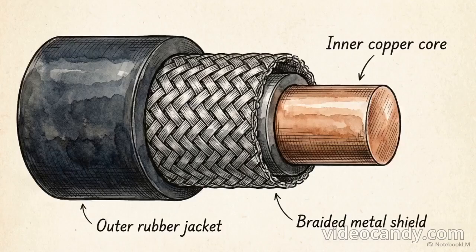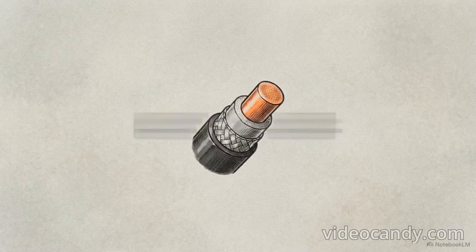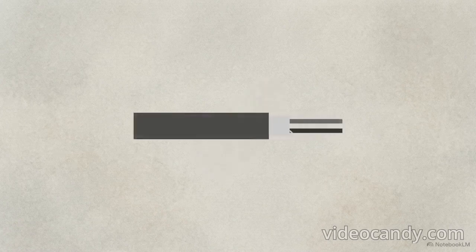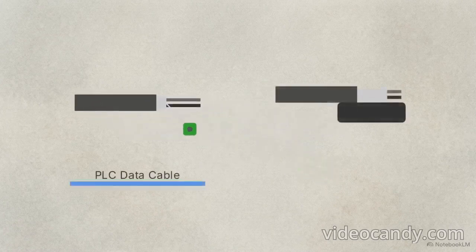The first defense is distance. Ensure your heavy power cables and your sensitive control cables are separated by at least 8 inches. They should never share the same conduit. Even with proper distance, you still rely on shielded cables, but a common mistake ruins that protection: stripping the shield back and twisting it into a long pigtail to reach a ground lug.